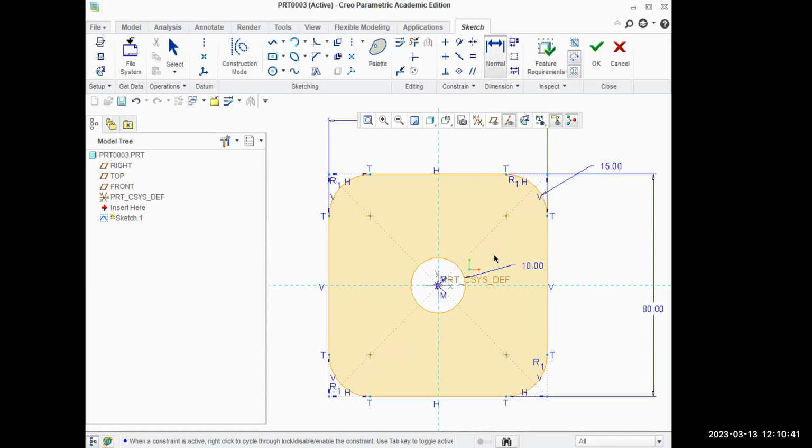Now we have to drop the pocketing slots here. Okay. Which consists of 2 tangent lines and 2 semicircles. Okay. But here there is a provision to make use of existing profiles. For example, if you click on a palette, you can see under palette profiles are there, then documents are there, shapes are there. Okay. So under shapes, you can find racetrack. Pick and drag this racetrack and place it here.